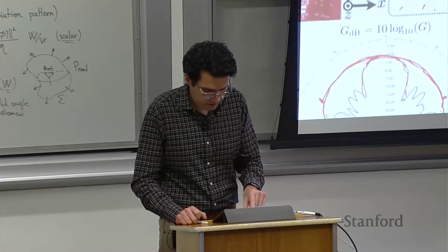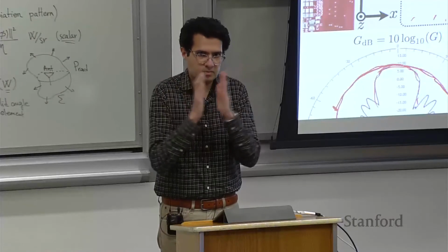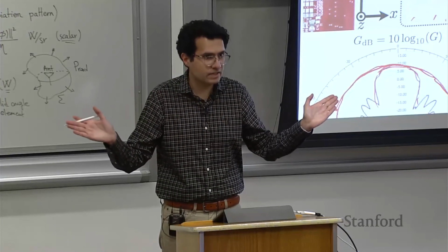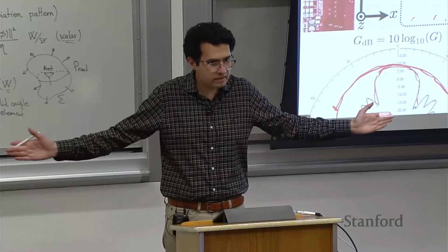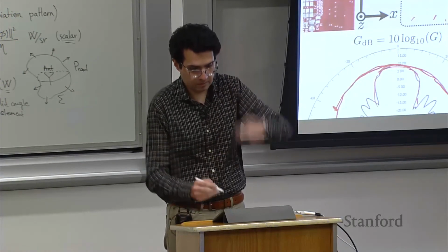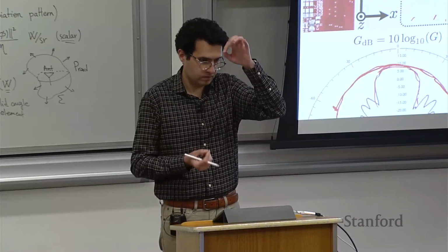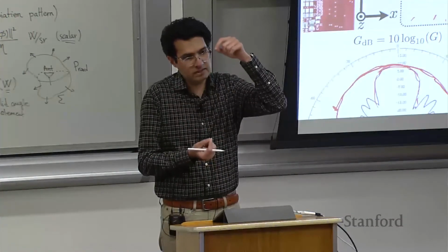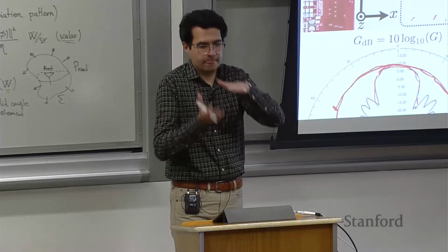And also from the geometry, it should make sense, because you see horizontally, the antenna has a very small aperture. And if you remember from the discussion in sonar, small aperture size means wide radiation, right? So horizontally, it's a small antenna, so you get wide radiation horizontally, and vertically it's a very long antenna. There's almost a factor of 5 difference between the vertical dimension and the horizontal dimension. So vertically it has a big aperture, which means you get a narrow radiation pattern vertically, okay?